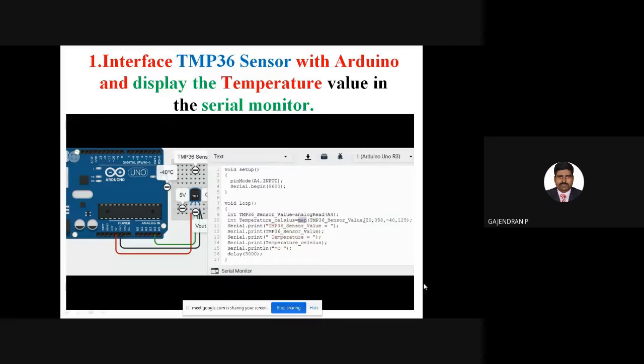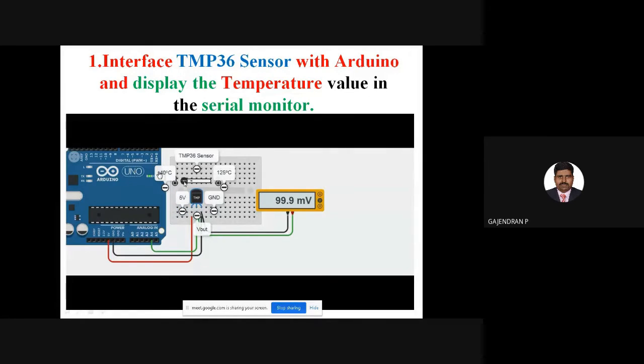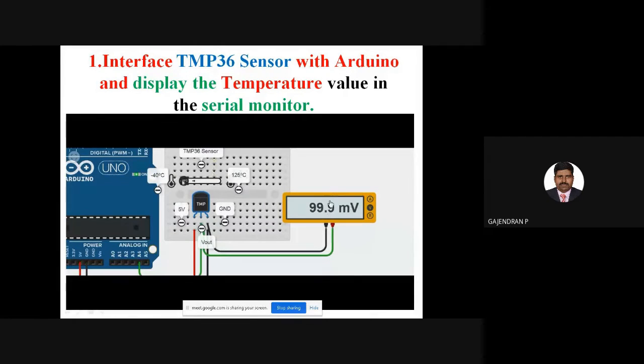Sir explained how to read the value, then how to convert it step by step. Here, if you have a multimeter, you can note down the range of voltages. See here, please observe, if I keep my sensor at the minimum temperature value, that is minus 40 degrees Celsius, this is my analog output voltage. Now I am going to increase the temperature to the maximum temperature. This is my 1.75 volt.